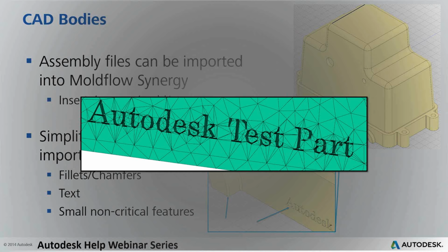And here you can see I just put an example of the text, so embossed text on a part. You can see here there's a lot of high aspect ratio elements. It might not necessarily call for warnings, or might be above the recommended range for these aspect ratios, but it's just something to keep in mind, again, when you're looking through that simplification process, to try to eliminate and simplify that as much as possible. Do we really need the text on there, the sans serif on there, or can we do without this completely?